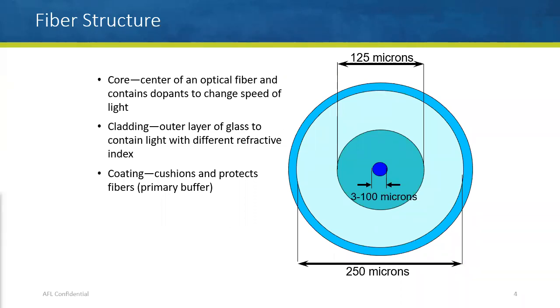It's hard to have a conversation about fiber selection without talking a little bit about what fiber optics are and how fiber works. In general, fiber is basically a concentric piece of glass. We have a couple different densities of glass. The glass down the center is what carries the light that you're after, and the glass around the outside has a slightly different density, so it has a different refraction rate, and that causes the light to bounce down the core glass down the center instead of just going out the sides.